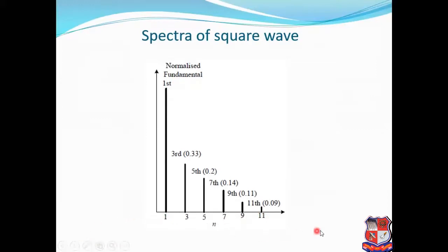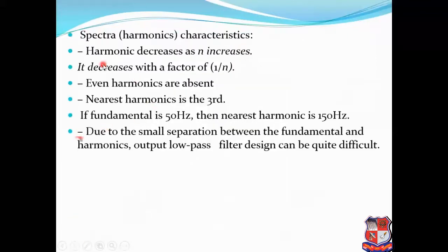As we increase the harmonic order, the harmonic content will be reduced for the square wave. So what we have studied from that is the harmonic spectrum decreases as n increases. It decreases with the factor of 1 by n, as we have talked. Even order harmonics are absent.